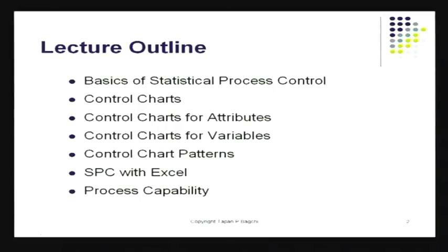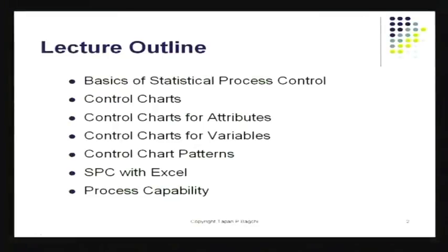Then we've got other types of quality characteristics where I can make a measurement. For example, the dimension, the length of this pen, or some dimension of the roundness of the tip, for example, those can be measured. And again, those measurements can lead to a set of control charts which are called variables control charts. You might have heard of the charts called XBar chart and range chart, R charts, and so on. Those come under what we call variables control charts. And charts like the P chart and the C chart and the U chart and so on, those come in the category of attribute charts.